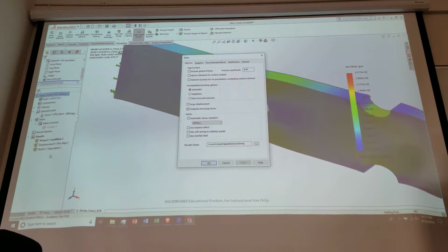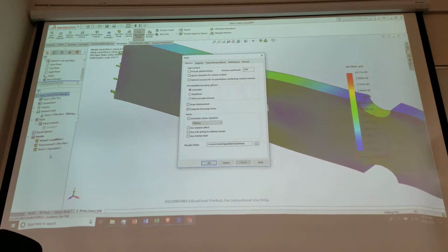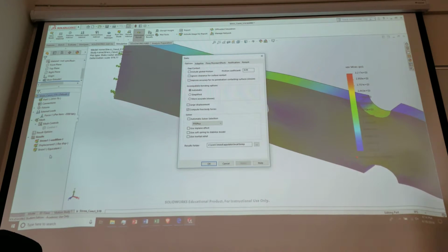F over A. Bending shear, you're saying? What's the stress in the beam back here? F over A. And what kind of stress is it? That's a normal stress, yes. That we tend to write as a bending stress.